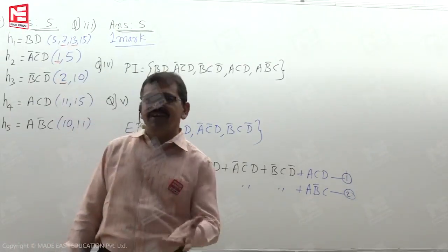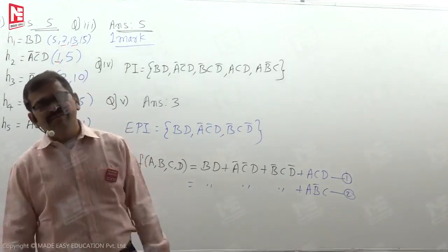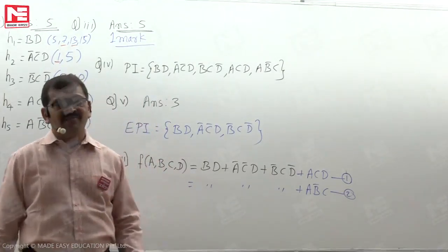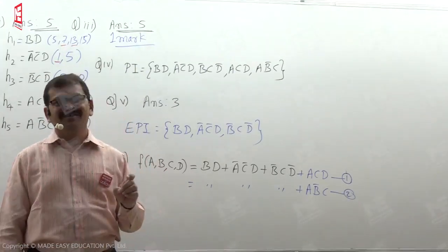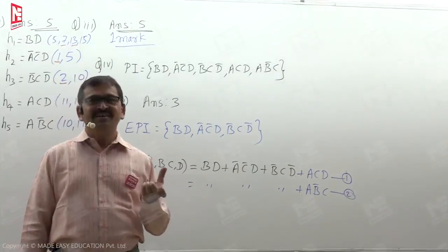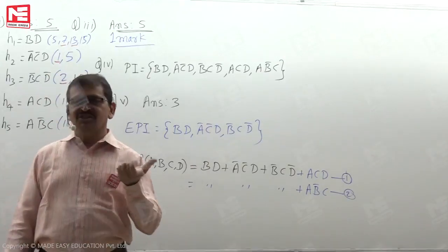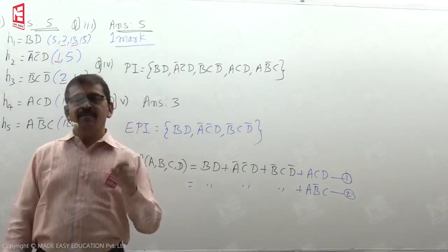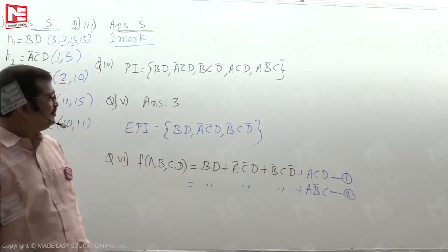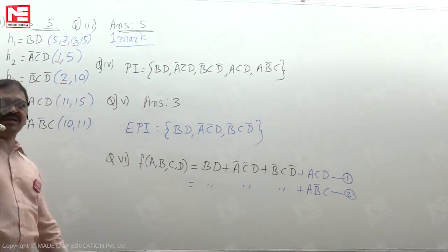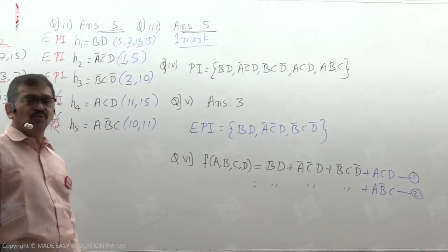But using the K-map, we are guaranteed to find the minimal form, and of course, all possible minimal expressions. That is why we said the K-map is a systematic procedure for finding minimal expressions. So on the whole, the function has two minimal forms.